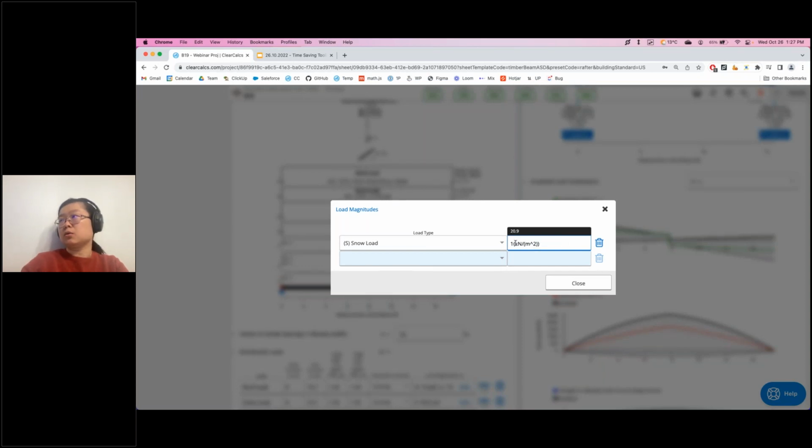And so we know the conversion from kilonewton to PSF is 20.9. And then you can do any type of math you wish. You can multiply it by 2. If you don't put in a number, we'll assume it's unitless. And then the cosine of 23 degrees. And you have to put in degrees, otherwise by default our trig functions come as radians.